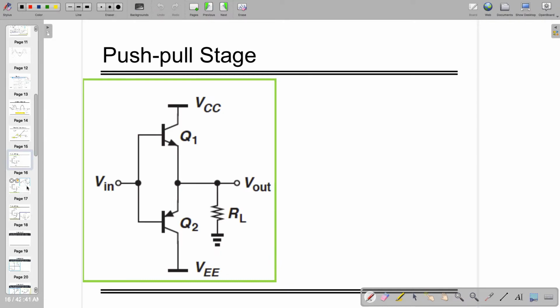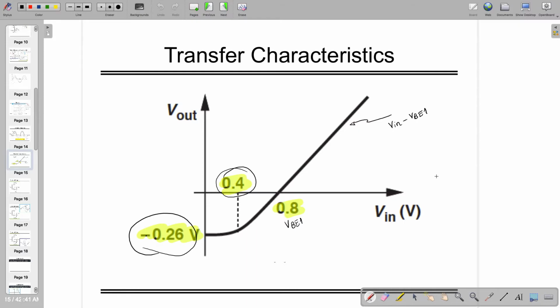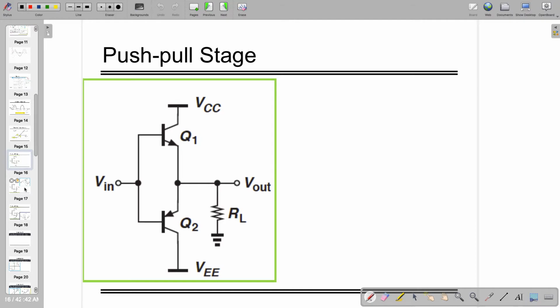Now my simple and best example is, because this one was always giving me output in the positive half with a little bit below 0 volt, but I cannot have the full swing in both positive and negative. So the most important thing is you can use some sort of push-pull stage, where you have two transistors, one NPN and one PNP. Both are acting as common collector amplifiers, and each follows the same characteristic as the single transistor. However, we are adding both transistors together, Q1 and Q2,